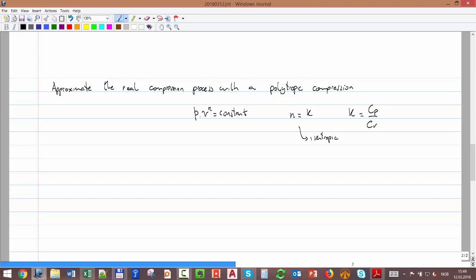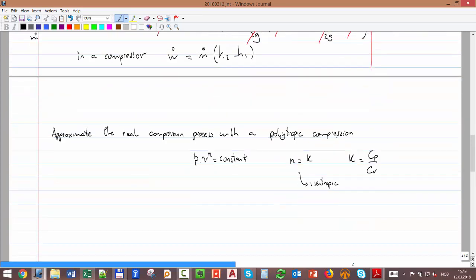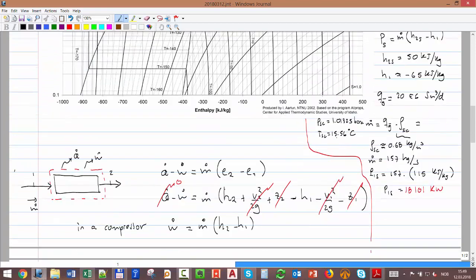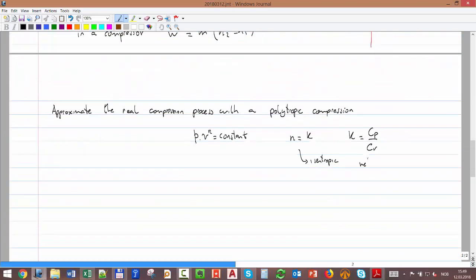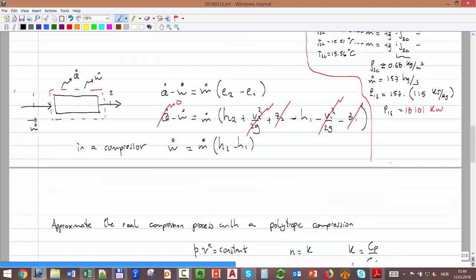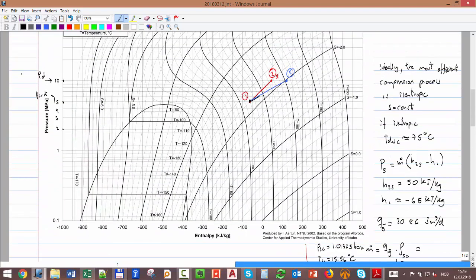I hope you thought you wouldn't have to use that knowledge again, but now I'm forcing you to use it again. So I hope it's not causing any short circuit in your brain. Okay, so that's the way. And actually, it will depend, but that number, for example, for methane, is 1.3. So I need a number higher than that to deviate from the isentropic path.